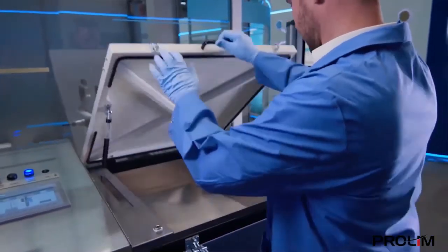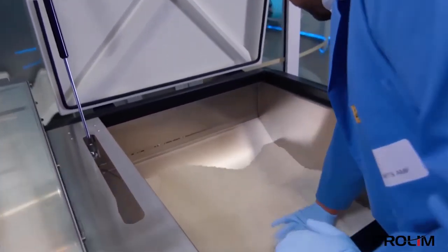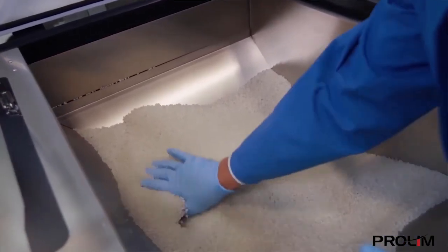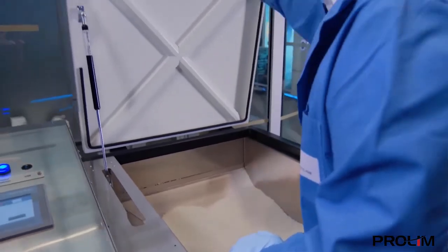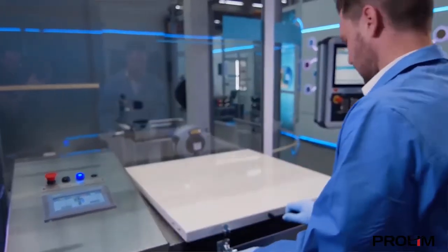Thanks a lot, Thomas. So meanwhile, I walked over to the real robot in the AMEC, and as you can see behind me, it is already printing. The average print time for the radiator duct mold of the race car is about 8 hours. So I already started printing it this morning. The setup for it took roughly about 20 to 30 minutes. So I needed to check the pallets, I needed to refill them, switch on the cabinets, and of course also some warm-up time for the extruder.